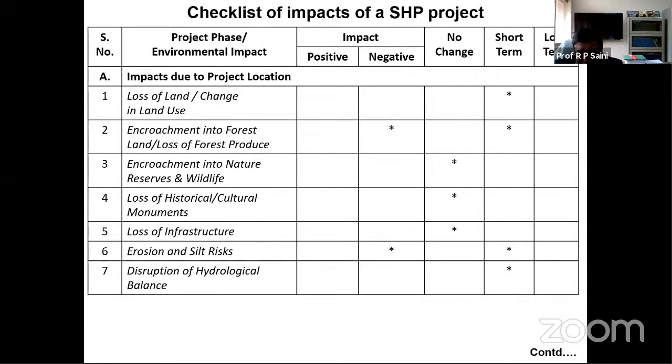Sometimes at some sites the developer wants to draw the complete water to produce electricity and doesn't follow the guidelines. If they follow the guidelines, there won't be any problem, because in some states you have to leave 20% discharge, and sometimes 10%, in the natural stream.